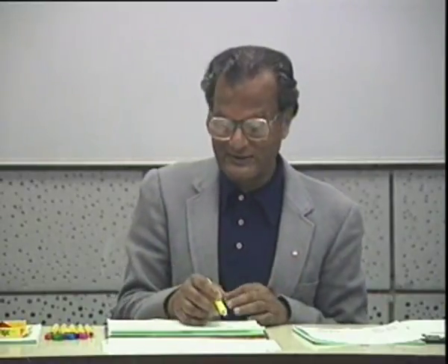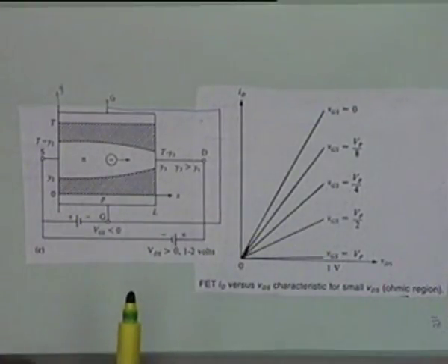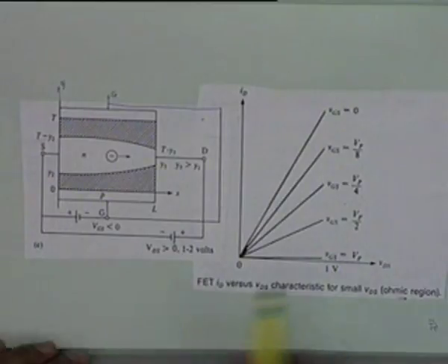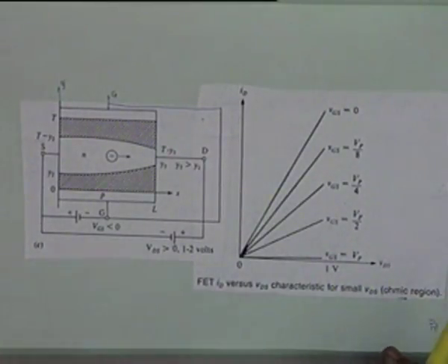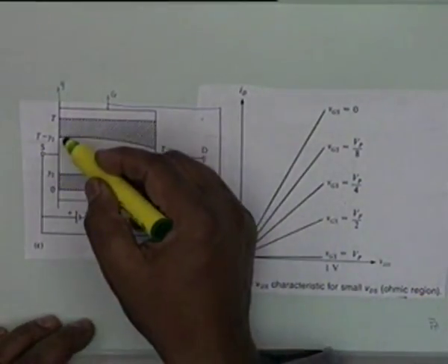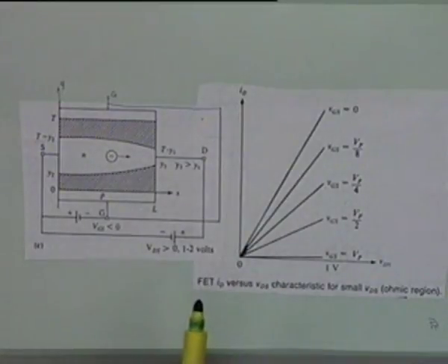If that happens, then you have emptiness all around. There is no electron, alas, no electron can cross to the other side. Correct? So when VGS reaches a voltage Vp, which is called the pinch off voltage, because the two depletion regions come and meet here, they look like a pincher, and the current becomes equal to 0. The drain current doesn't flow.